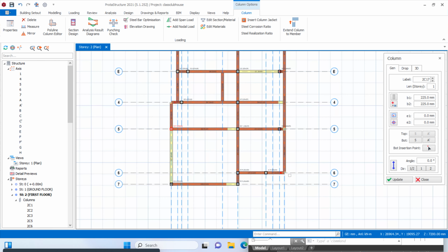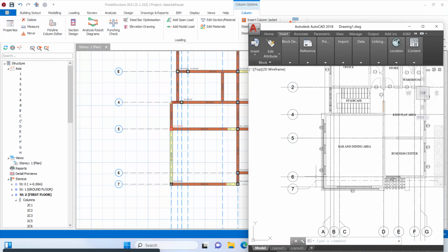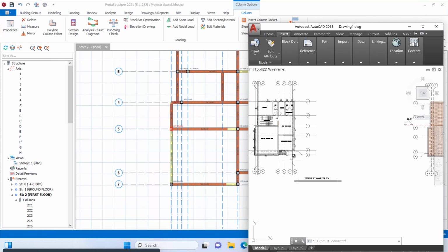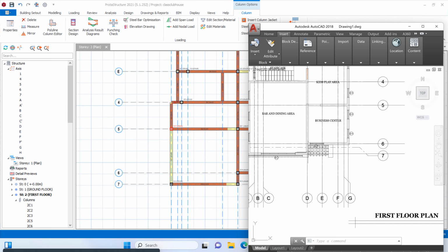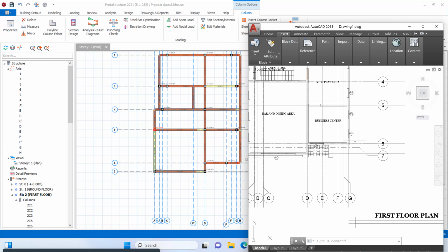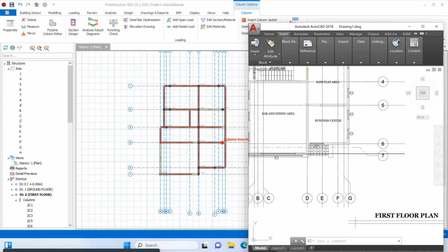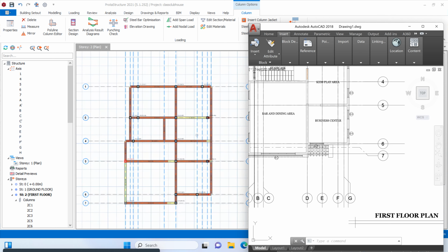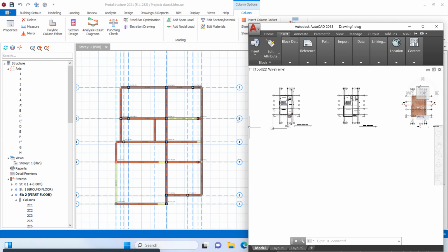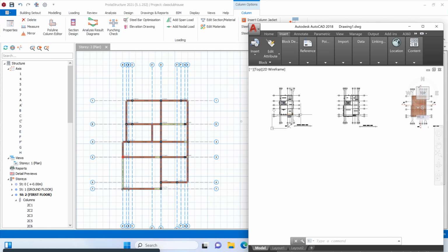So at this place, let us check our architectural design again. First floor. This is what we have. At this stage, there's no window for this one here. This column can still maintain. At 5, there's a wall here. I can maintain this column. At E, it's not supposed to be E, but rather 2.